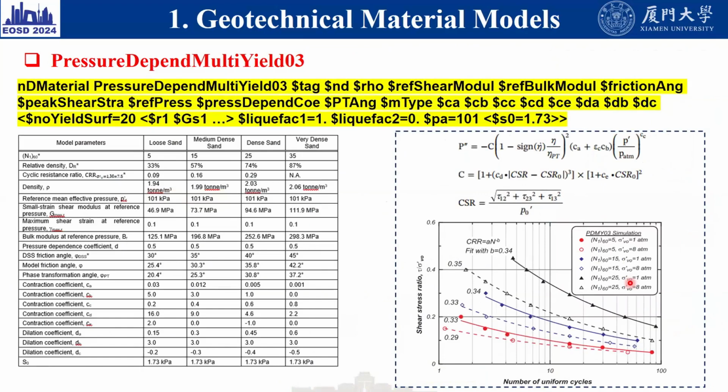So what's the difference between 0.2 and 0.3? The only difference between the 0.2 and 0.3 model is that the contraction rule is updated. Why do we need to update it? Because in practical engineering, people only care about the blow count, the SPT blow count. People just care about a number, for example the soil SPT value in practical engineering is 5. But our soil model has too many parameters, more than 20, so it's impossible for them to use.